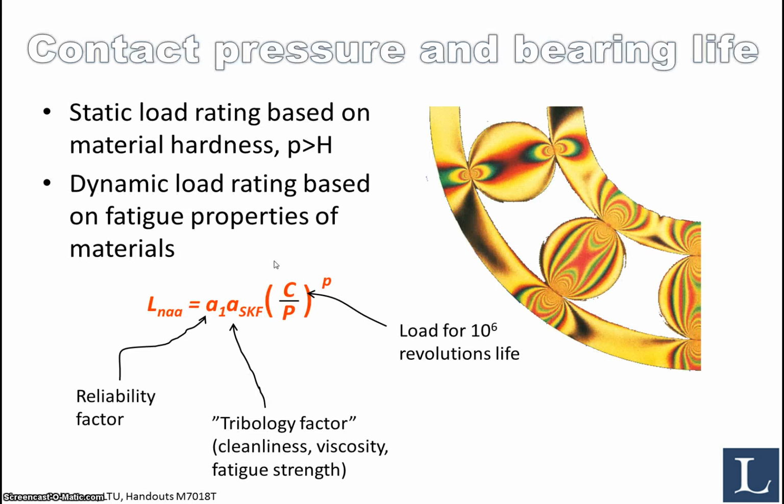Now, there is also a more extended formula where you have a reliability factor that accounts for the probability of a bearing to exceed a certain life, and the tribology factor, which you see right here, which accounts for cleanliness of the lubricant, the viscosity, fatigue strength, and so on.